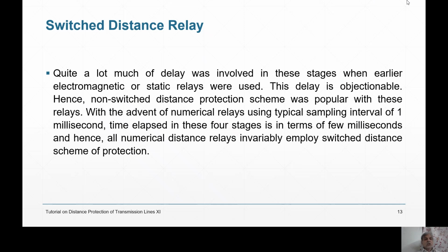So because of fast digital signal processors, fast microprocessors, and fast mathematical techniques used in numerical relays, most numerical relays now, or I should say mostly all numerical relays invariably now use switched distance relays, in which all these 4 procedures, 4 steps, are required to be done.